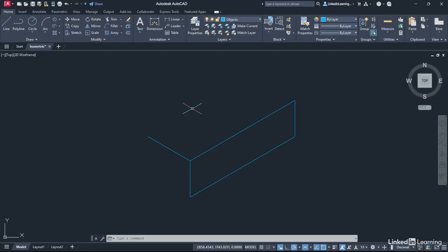Now you'll notice the crosshair looks a bit different. That's because we're using the isometric drafting in AutoCAD. In the previous video we did the ellipses using that 60 degrees isometric rotation tool in the ellipse command. That's what we're working towards in this drawing, but we're actually drafting in isometric, which is normally at angles of 30 and 60 degrees. And we're going to generate a 2D isometric representation of a 3D rectangular solid. It sounds very complex. It isn't. It's simple drafting using isometric angles.